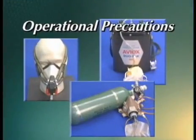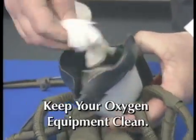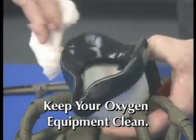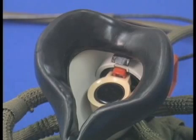This pertains to all general aviation aircraft, whether pressurized or unpressurized. Some operational precautions to use with all oxygen systems are: keep your oxygen equipment clean. For proper cleaning instructions, check with the manufacturer of the mask. The interaction of oil-based products with oxygen creates a fire hazard. Additionally, oil attracts dirt particles, which contaminate storage containers, regulators, masks, and valves.